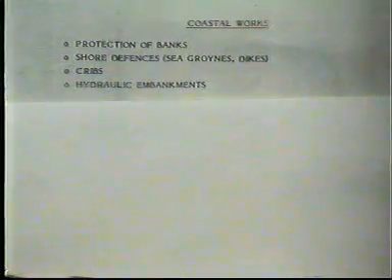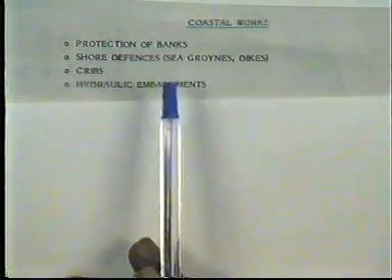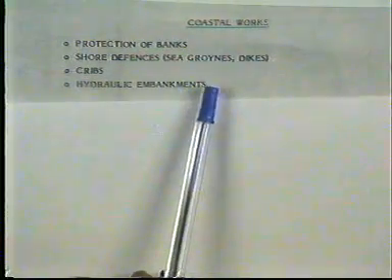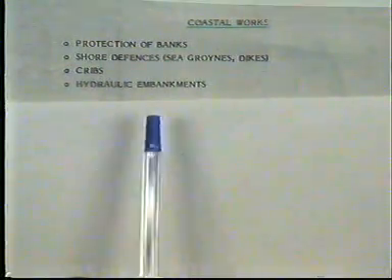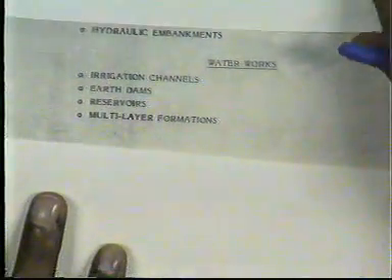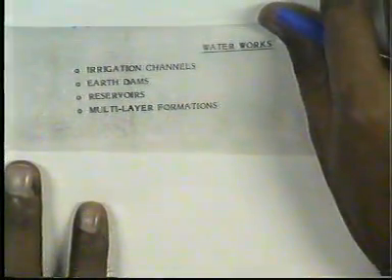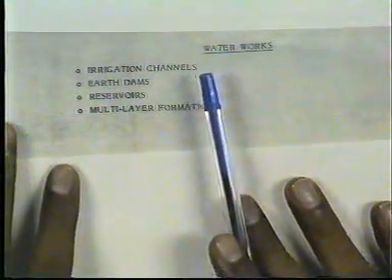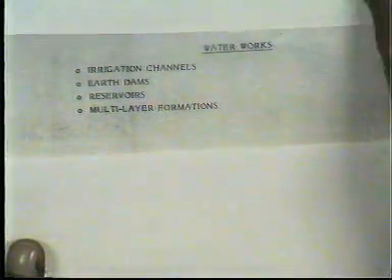It can be used also in coastal works: protection of banks, shore defenses, sea dikes, also in creeks and hydraulic embankments. Geosynthetic material can also be used in water works, such as irrigation channels, earth dams, reservoirs and multi-layer formation.